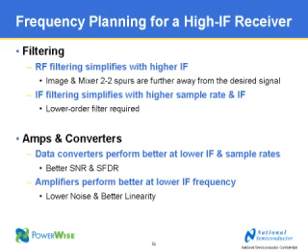Okay, so I guess, Bobby, you've given some example looking at filtering. The next thing that we need to do when we're building this system is handle the frequency planning. So when we talk about frequency planning, we're really talking about picking an IF frequency and picking a sampling rate for the ADC. Correct. Now, it turns out, unfortunately, that there are conflicting requirements.